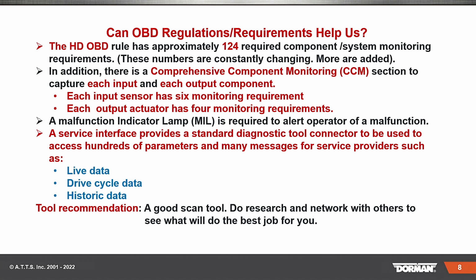Each input sensor has 6 monitoring requirements. Each output actually has 4 monitoring. And of course, just like you have with light duty, you've got your malfunction indicator lamp. That is a requirement to alert the operator of a malfunction. And the service interface provides a standard diagnostic tool connector to access hundreds of parameters, and it's nice to get at the live data, drive cycle and all that stuff, historic data.